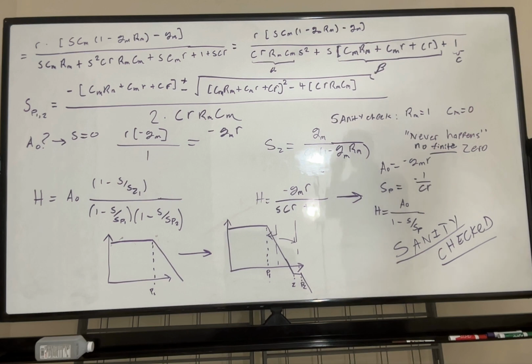Great. Now, if we say that CM equals 0, we can take a look at our transfer function again up here. And this will go to 0, this will go to 0, this will go to 0, but not this. And this will go to 0, which will lead to this transfer function. And what do you know? That's also the exact transfer function if you only had the load capacitor. For some reason, I started writing C instead of CL here.